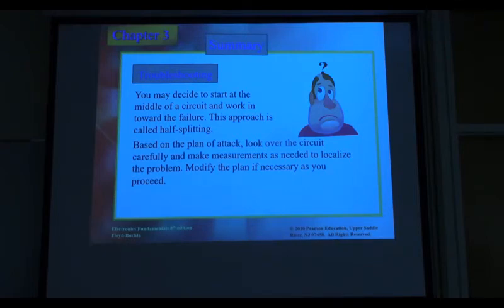You need to learn how to use the multimeter to measure the voltage, the current, the resistance, possibly the capacitance and inductance. Later, at a higher level, you are going to use more advanced equipment, for example an oscilloscope, to look at exactly what the waveform looks like, for example a sine wave, square wave, or triangle wave. All these are used in troubleshooting.